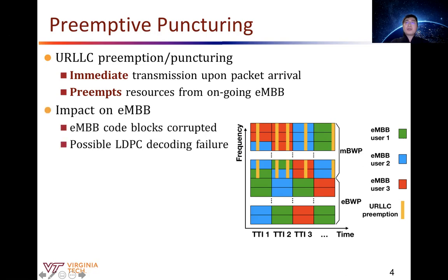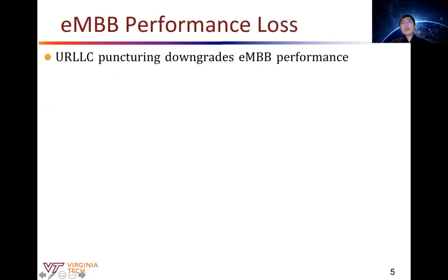Although this preemptive puncturing scheme can effectively minimize the latency of URLLC, the downside is that the eMBB performance will be adversely impacted. In particular, the LDPC decoding of an eMBB code block may fail due to the puncturing from URLLC. More formally, preemptive puncturing will result in eMBB performance loss in terms of both data throughput and link reliability.